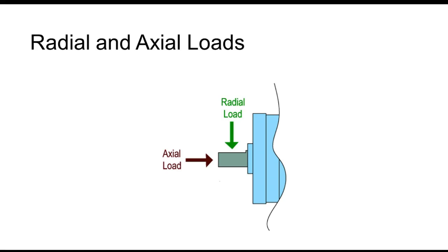Yeah, one of them is pressing basically, and the other one is pushing or pulling. So anytime we have these gears, and anytime we have bearings and stuff like that, we're very concerned with radial loads and axial loads, right? So if we got a heavy axial load, then we wouldn't use the same bearing that we would use for something that had a heavy radial load.